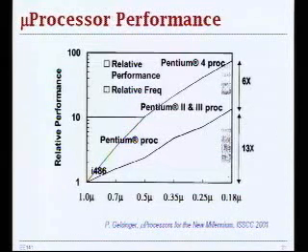Microprocessor performance, if you look just at the pure technology scaling model, going from 1 micron and scaling all the way over time to 0.18 micron, then you can see that over these 1, 2, 3, 4, 5, 6 technology generations, you have about 2x improvement for each generation. So it's about 12, 13x improvement in performance just due to technology scaling.